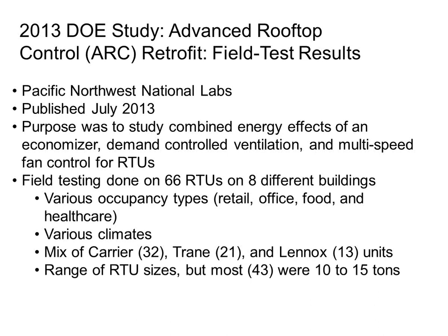And the majority of the rooftops in the study were in the 10 to 15 ton range, which is sort of the sweet spot for some of these technologies. Because if you put some of these things on smaller units, the payback might not be there. And you put them on bigger units, well, they may have already had them on the bigger units because of code reasons anyway. So this is kind of like the sweet spot, although it does apply to bigger and smaller units.